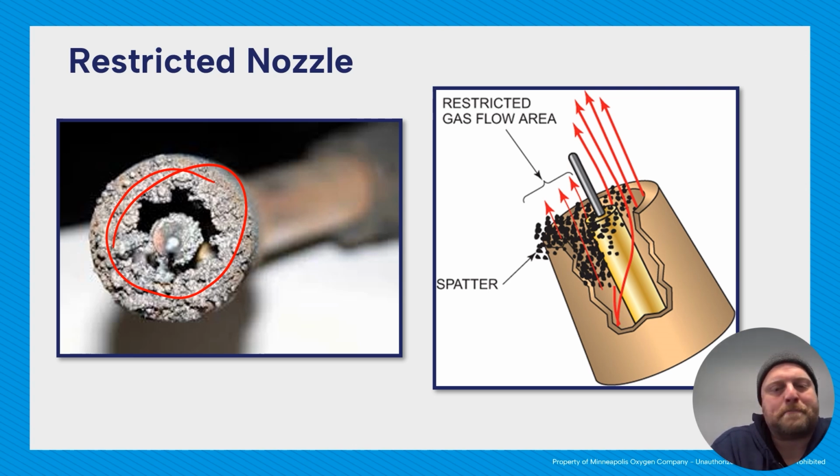And one of the things you do is you pop that nozzle off, you stick the two, I guess, tines, I don't know what exact word would be, of the welper into that nozzle, spin it around a few times, knock all this junk off, and then you're good to go. You're not going to have that restricted airflow.